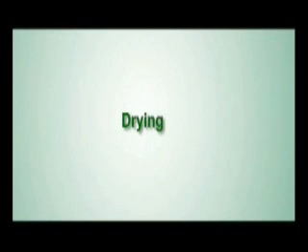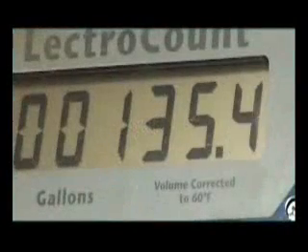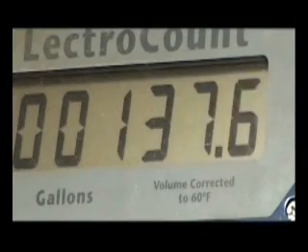In heat treating, drying poses several issues. Removing moisture from wood requires BTUs, which costs money. Drying wood can cause splitting, cupping, twisting, and other degrade problems, as well as cause wood nailed together to produce pallets, boxes, and other packaging products to split.